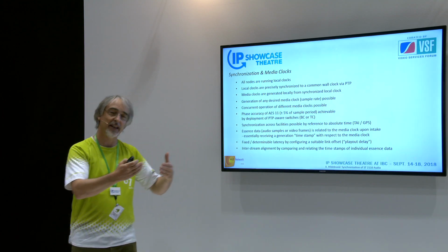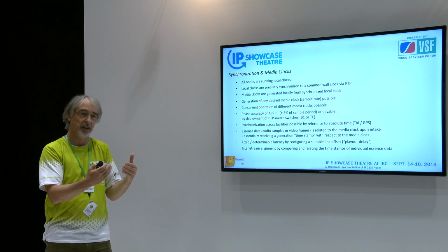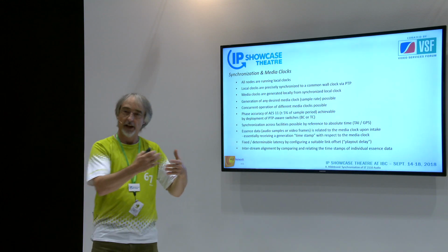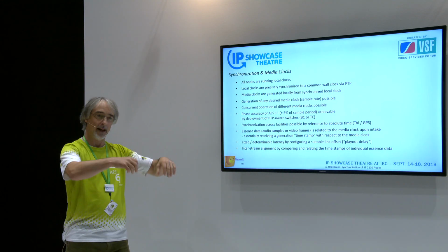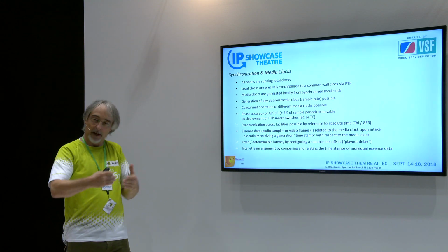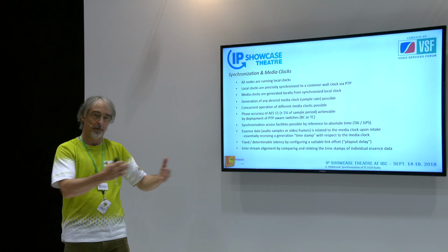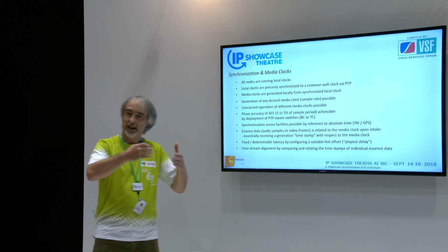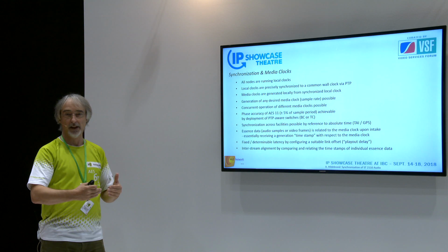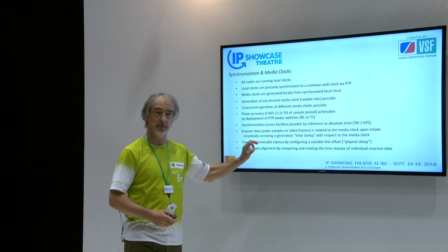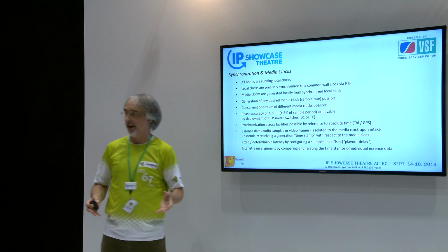I can now exactly determine I want to have a 2 millisecond processing latency in order to cope with any potential network jitter. And now I can exactly match the samples which are stored in the packet in my playout buffer so that samples which have been gathered at the same point in time can actually correlate for the further onwards processing. So that's the magic behind the timestamps. This is why we all need time in the system.